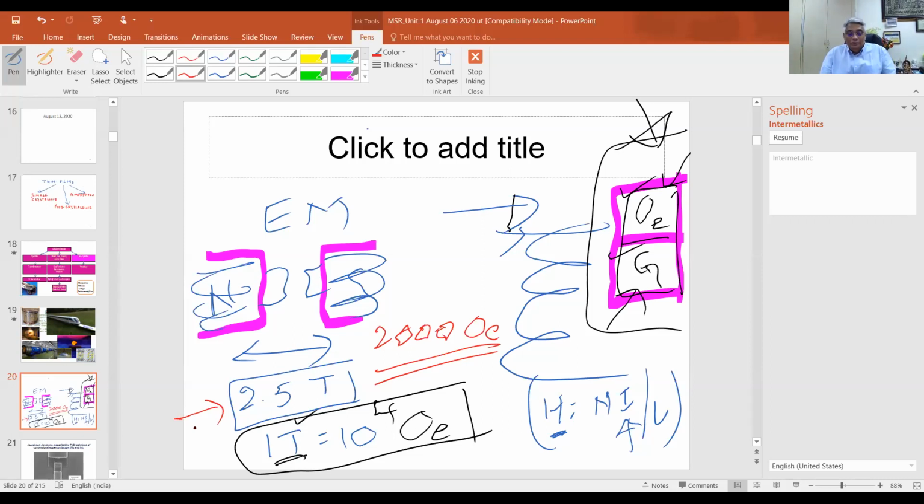And of course, to get 2.5 Tesla, you need to be passing a significant amount of current to these coils, almost of the order of 10 to 20 to 30, 40 amperes of current, depending on the field that you want to generate. So the limit of 2.5 Tesla is basically on the diameter of this coil, and also the upper limit of current that you can use.